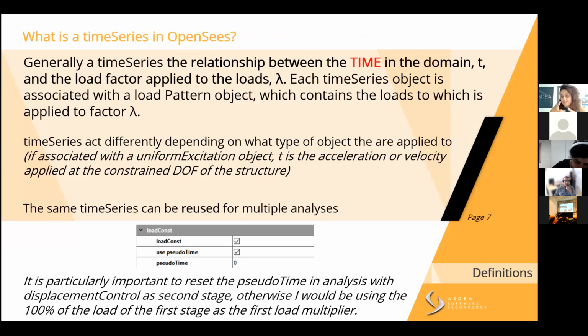So for example, if you have different loads that you want to apply with different time series, for example, keep some loads constant and make some other loads increase linearly, you can create different time series and different load patterns and apply, let's say, different behaviors of the load factor application in the same analysis. So this is something that can be useful.